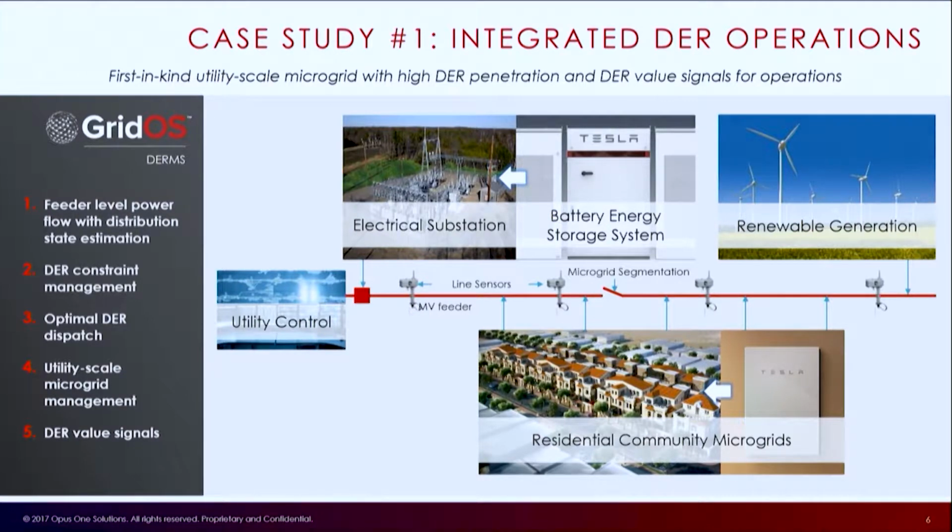So the project that we are embarking on is to deploy a large battery storage system at the substation to work alongside the wind generation to look at power quality, peak reduction, renewable integration, but also a full-on feeder level utility scale microgrid to essentially island the feeder and that community and work using the wind and the battery in times of outage, either on the sub-transmission line or further downstream on the distribution system.